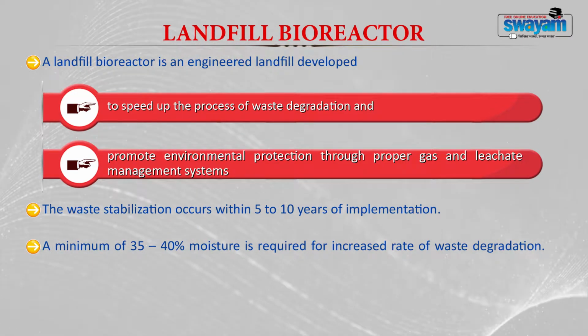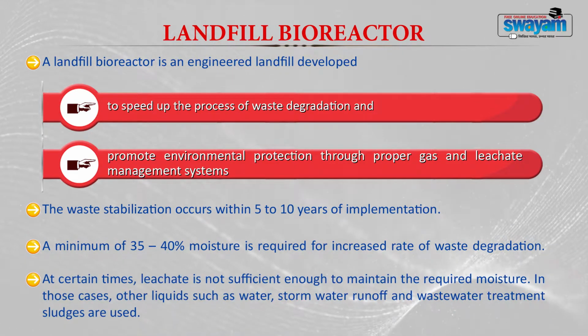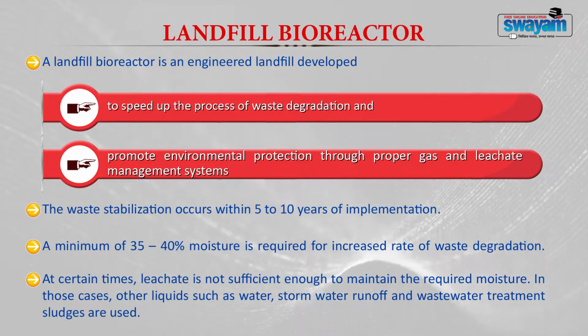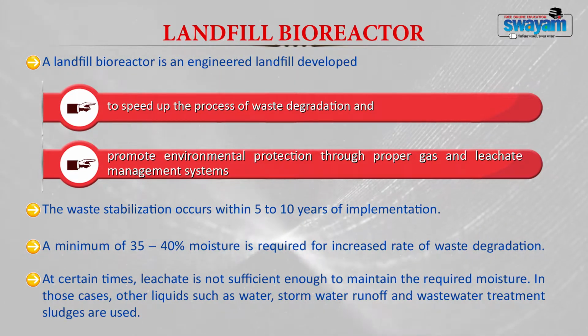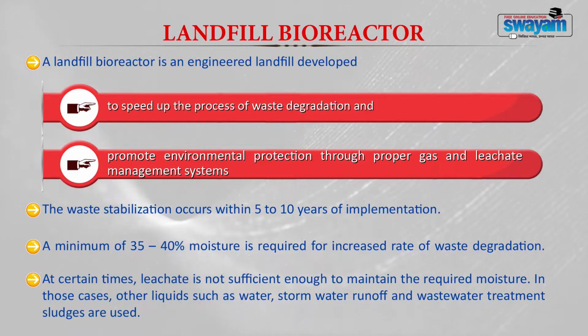The moisture level is generally maintained by recirculating leachate, which ensures that the moisture within the waste is maintained. If the leachate is not sufficient, then you can use water, storm water runoff or wastewater treatment sludges.